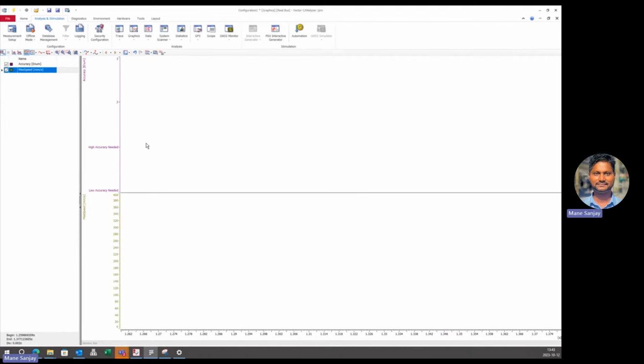I want to see the torque and I want to see the measured speed differently. So here I can add the cursor. This window is basically where you can add the cursor. If I add this cursor at the same instant where, let's say, torque was suddenly falling down, at the same time, what is happening with this max speed signal, or what is happening with the thermal temperature, the thermal behavior, the thermal component of any system. So that way you can add multiple signals and do the analysis.